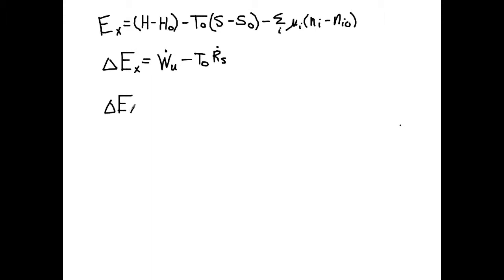From this equation, it can be seen that the exergy change is a balance of useful work and the entropy production term, which can be regarded as work loss because of irreversibilities. For a reversible process, R equals 0, and thus the exergy change of a reversible process equals the most useful work associated with a work-producing process or the least useful work required by a work-consuming process. It is evident from the foregoing that the exergy change and the creation of entropy are the energy bounds of the process.